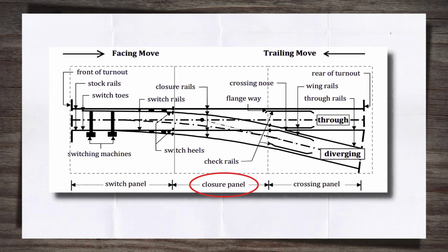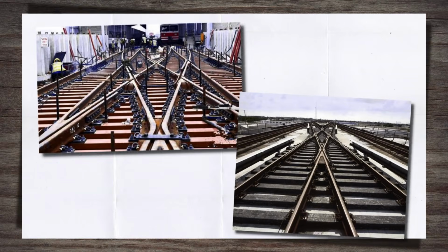It is also worth noting here that one of the other main features of a junction that may jump straight out at you is the long sleepers, known as bearers. With the diverging routes and all that, you cannot use standard sleepers. Bearers are extended in length to hold multiple rails across 2 or more tracks. They also tend to be wider to take the extra load and other forces present at junctions.